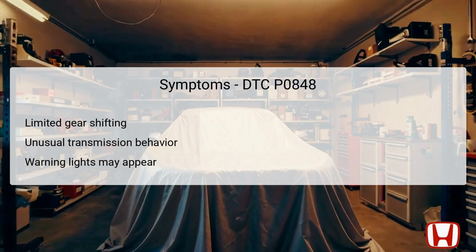Several symptoms can signal the presence of DTC P0848 in the Honda Pilot. One prominent symptom is limited gear shifting, where the vehicle may only shift between third to fifth gears due to the fail-safe mechanism engaged by the PCM. Additionally, drivers may notice unusual behavior from the transmission, such as slipping or jerking, as the vehicle struggles to engage the appropriate gear, leading to a less smooth driving experience.